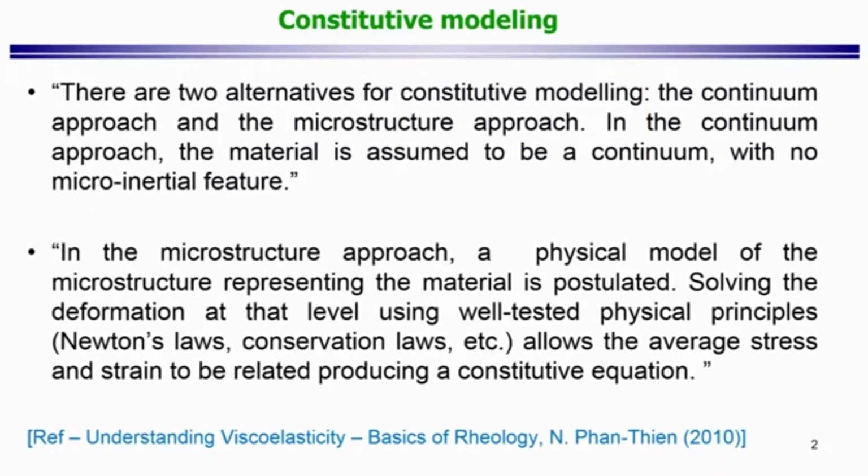In contrast to the continuum approach, you have the microstructure approach, where he says that in the microstructure approach, a physical model of the microstructure representing the material is postulated. Solving the deformation at that level using well tested physical principles like Newton's laws, other conservation laws, etc., allows the average stress and the strain to be related, producing a constitutive equation.